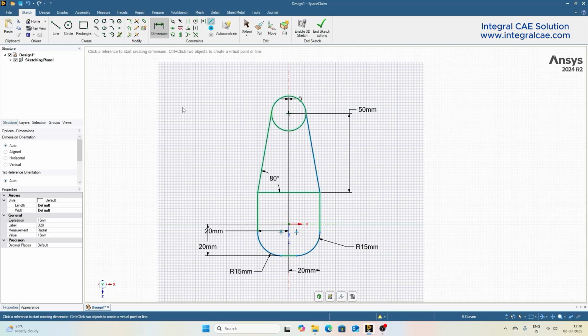It is however not necessary, due to the reason that SpaceClaim does not store the sketch information once the 3D models are created. We will know about that in some other session. There is also one more reason why this is important though. If you assign a constraint to the sketch objects, like the tangency we have seen here, the constraint will always be maintained and respected whenever you change any other dimensions and move any other lines or curves. Let's look at these options.